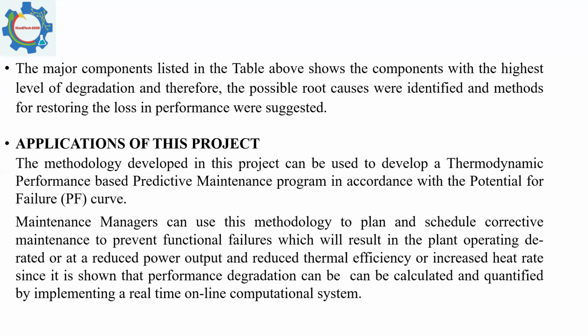So the next step is to actually use the actual operating parameters and calculate various efficiencies on the basis of the first law, on the basis of the second law, and compare it with the design efficiencies and design performance parameters, so that you can actually see if there's any degradation. So if this is done in real time online, it means that you could actually trend that degradation or deviation in performance on the basis of both the first law and the second law.